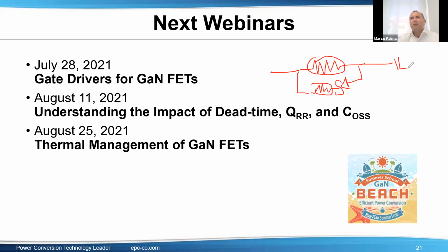This is not good for GaNFET. The reason is this diode drop is already 0 point something, let's say 0.3 volt, and the threshold of a GaNFET is definitely smaller than a threshold of a MOSFET. So just by putting this, you're jeopardizing the possibility to Miller clamp the gate. So it's better to always have a gate driver with double output, which is made for GaNFET.